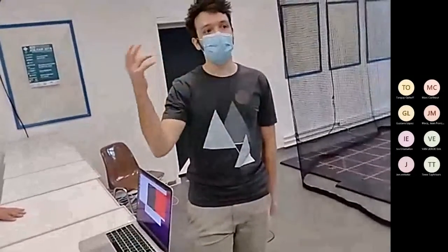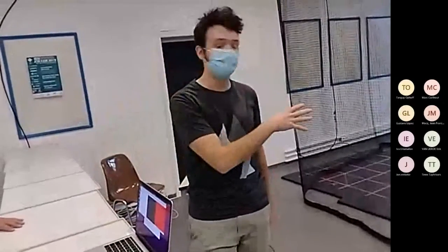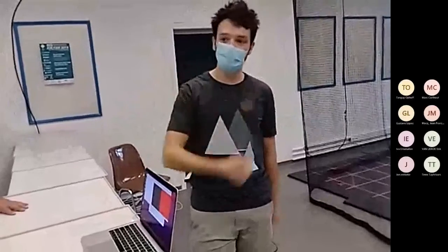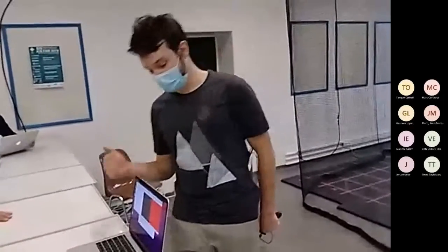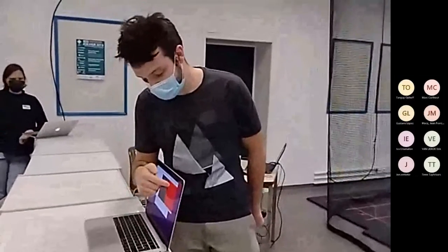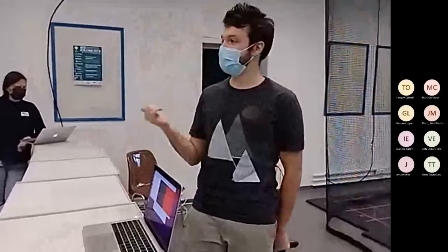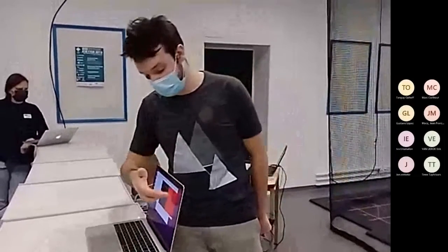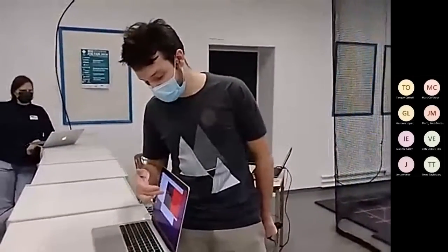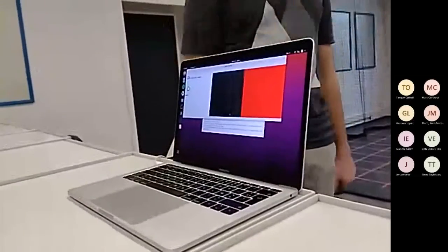I want to augment my dataset in such a way that it can fly directly in the real world without any real world data collection. My neural network takes the RGB input and decodes a semantic map, where it indicates 1 if it's a line and 0 if it's not. From these same features, it also decodes a waypoint, and this waypoint is then sent to the PID controller to navigate the drone.